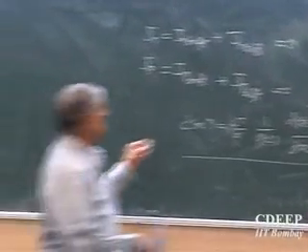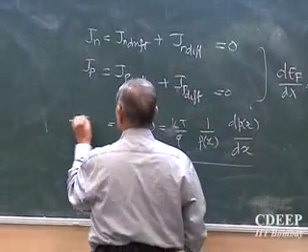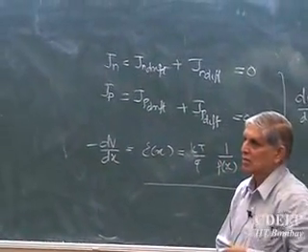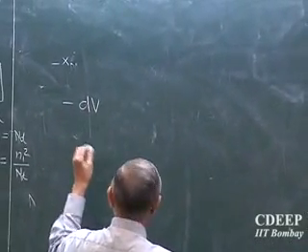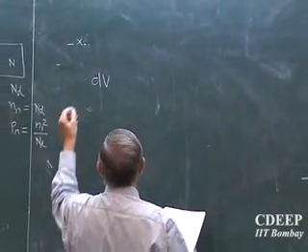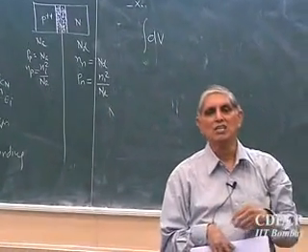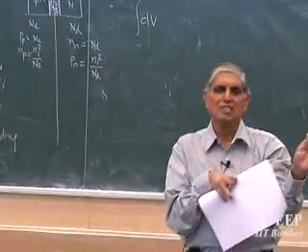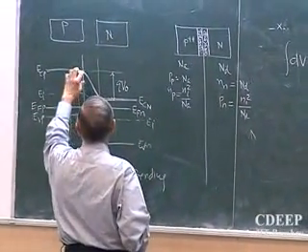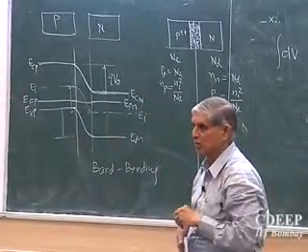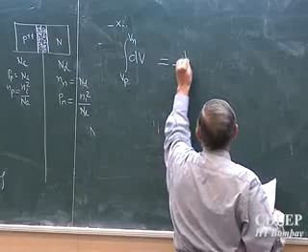Okay, what is Ex, it can be written in terms of voltage. E in terms of voltage gradient. E is minus dV by dx. So I want to solve this equation. So I say minus dV, okay, or you can also call plus dV, sign I will change on the other side. When I go from P to N, the voltage changes from Vp to Vn. Okay, let's say some potential at the edge of the depletion region is Vp, somewhere here, and some potential here is Vn correspondingly. So I integrate this, Vp to Vn, is equal to minus kT by Q.